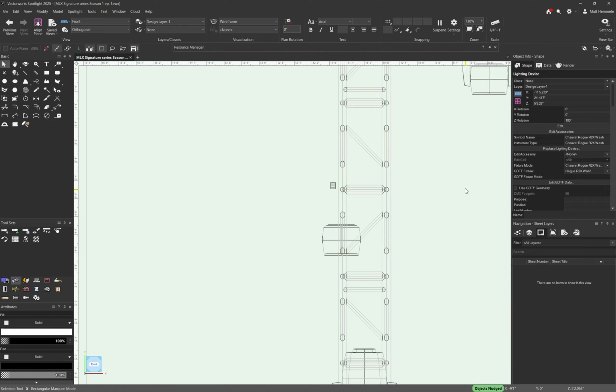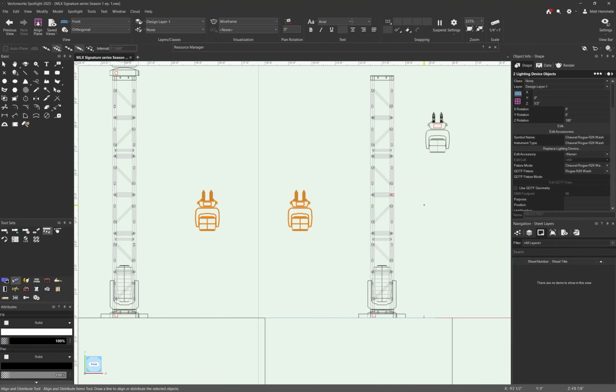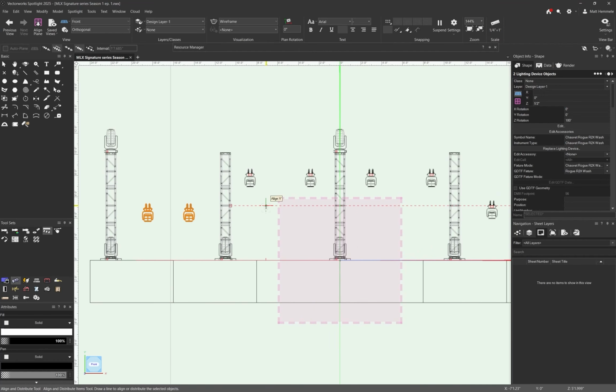What that red light is telling you is, basically you can add lights as a load to a truss. We don't want to do that with this. So we're just going to move this a foot off, or what we're going to do, we're going to select these. Select these. Go to lights, or excuse me, line and distribute. And we're going to do our evenly inside points mode. And to get the biggest spread, I'm gonna go to the outside of the truss, and I'm gonna land that there. And I think that's gonna fill in our negative space nicely.